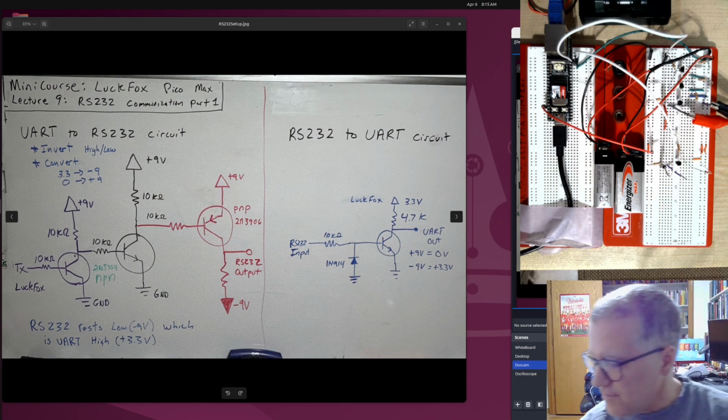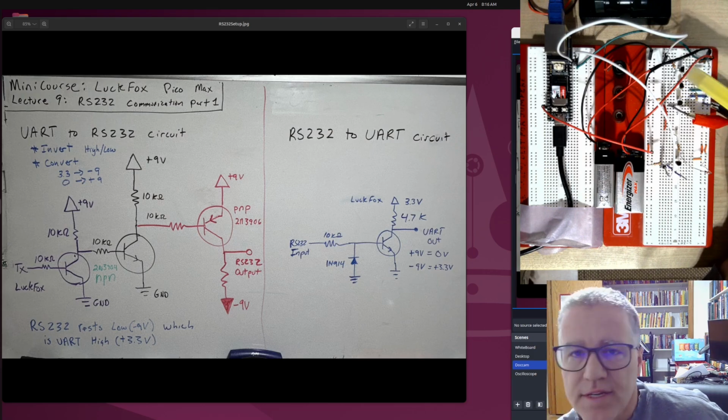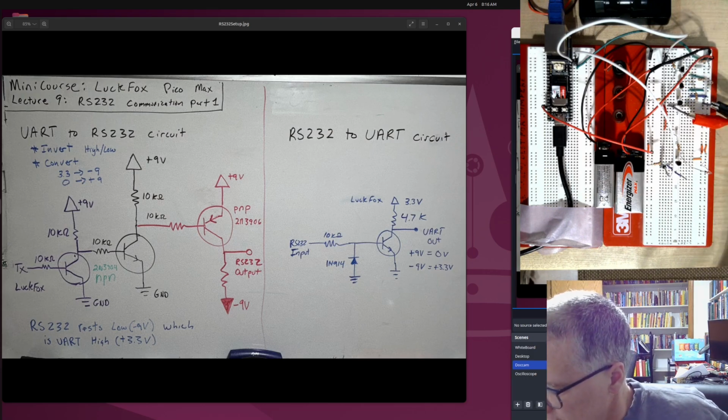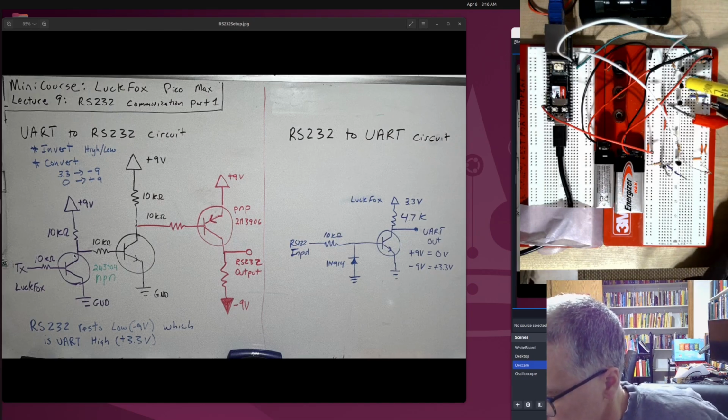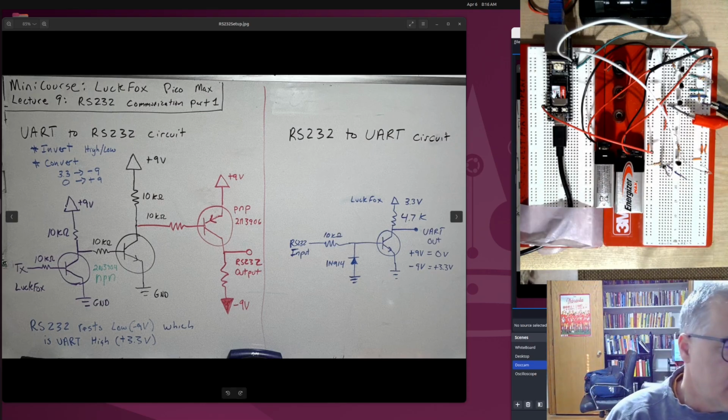Now coming off of the collector side is another 10K, and that's taking us to the base of the next transistor. So that's sitting right here. And so again, front side facing this pen. So emitter, base, collector, emitter grounded just like before, and then the collector taken up to the 9-volt rail with a 10K. So very similar situation here, this and the ground here.